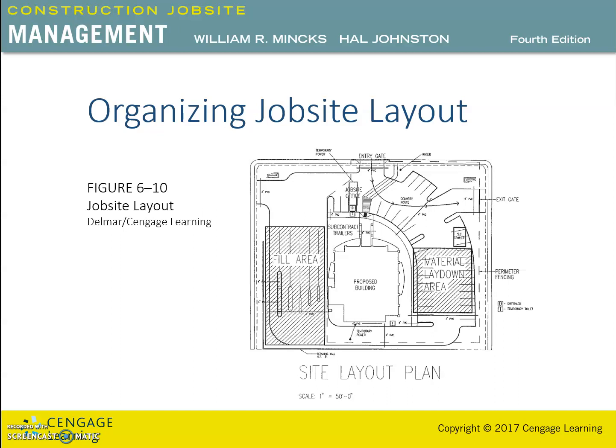Local codes have to be considered. Safety standards have to be followed. The data on the size of the larger lifting loads have to be determined accurately. Information from the subcontractors on the storage needs. Budgets should be established. And of course, many other factors, which include the other site features, need to be considered for creating a job site layout.